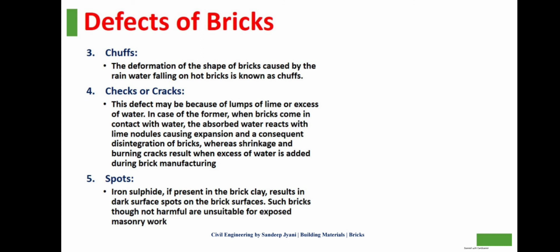Spots. Iron sulfide, if present in the brick, results in dark surface spots on the brick surface. Such bricks, though not harmful, are unsuitable for exposed masonry works.